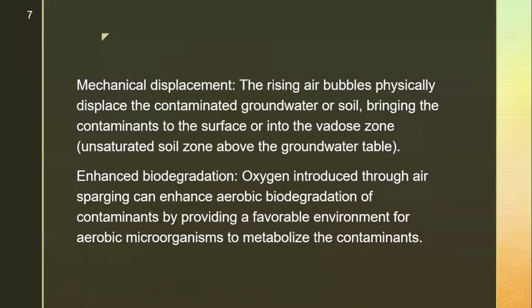In the context of in situ air stripping, or air sparging, volatilization occurs when volatile contaminants in the groundwater or soil transfer from the liquid or solid phase to the gas phase as air or oxygen is introduced into the subsurface environment.